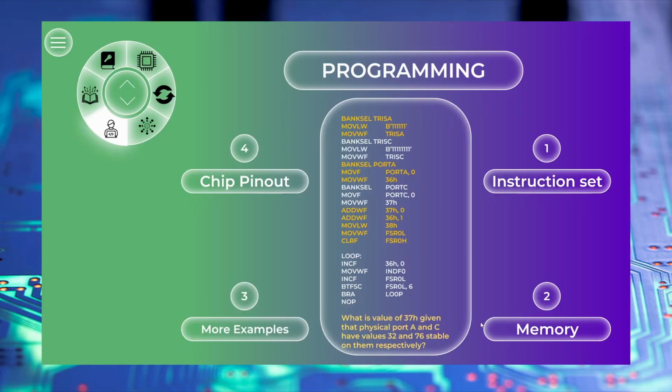We are going to look into how the memory of the microcontroller you are working with is organized. This is very important for you to know. The memory of the microcontroller includes what are called registers. And we have 4-bit registers, 8-bit registers, and 16-bit registers. Registers are just memory sections with bins known as bits. 8-bit registers have 8 memory bins, with each bin capable of accommodating 1 bit, a 0 or a 1.